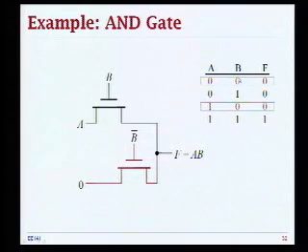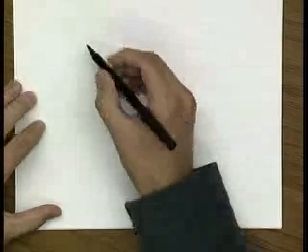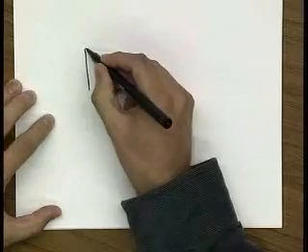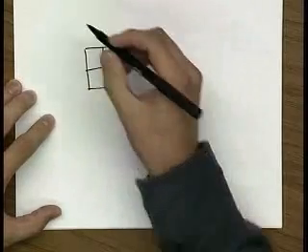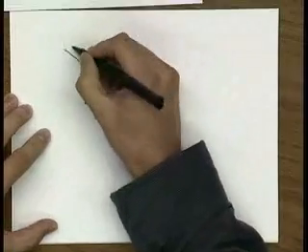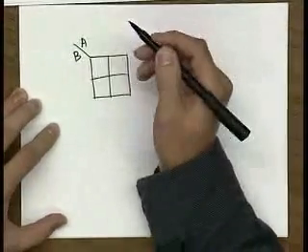So basically when B is equal to 1, your F is equal to A, and that's implemented with this transistor. When B is equal to 0, then your F is also equal to 0. And actually you can do this in a much simpler form. I used to do this a couple years ago to play with pass transistor logic, and you can read the papers on my website if you're interested. But you can do this very easily with a Karnaugh map.